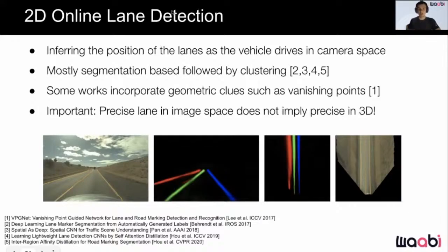For example, in the image below, we show the results of predicting the probability of the lane boundaries in 2D and then reprojecting them onto overhead view. The input camera image overlaid with the predictions from Pan et al. is shown on the left. The lane probability output of the model in camera view is shown next, followed by the reprojection of the probability output into an overhead view. Although the lane detections in camera view look quite precise visually, the probability output becomes diffuse with increasing distance, and the detected lane boundaries become less accurate in 3D.